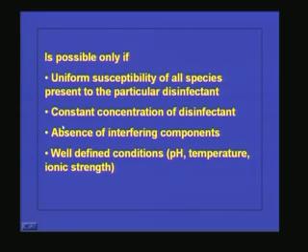and the second important point is constant concentration of disinfectant. But we know that when we add the disinfectant to the water, with respect to time, the concentration of the disinfectant or concentration of the chemical will be getting reduced. So at a reduced concentration, the effect on the microorganism will be less. So Chick's law is not considering that effect also. So that law is considering concentration of the disinfectant is remaining same, or concentration of the disinfectant is not having any effect on the disinfection or rate of kill, but that is not true.